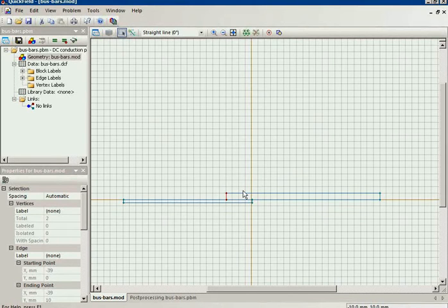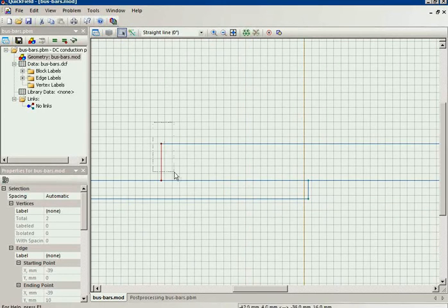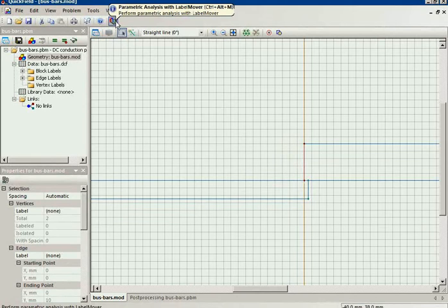It is an interesting task to run the series analysis and calculate the resistance for different contact area positions. QuickField has a tool to automate these calculations. It's called the label mover. Label mover may automate this calculation. It operates with the labeled objects.